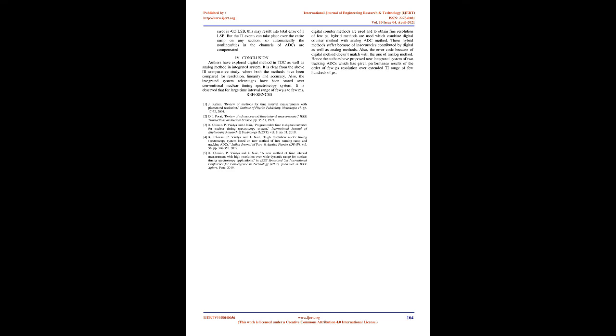The authors have proposed an integrated system which makes use of a SAR 16-bit ADC which has a low conversion time of 1 µs and very low acquisition jitter of a few ps. Those SAR ADCs offer low conversion time, which enables the system to digitize high event rates. SAR ADCs do impose limitations on the system because of wide DNL error. However, the proposed integrated system makes use of 2 ADCs which are tracking ADCs. So if one ADC's DNL error is plus 0.5 LSB, and the other ADC's error is minus 0.5 LSB, this may result in a total error of 1 LSB. But the TI events can take place over the entire ramp on any section, so automatically the nonlinearities in the channels of the ADCs are compensated.